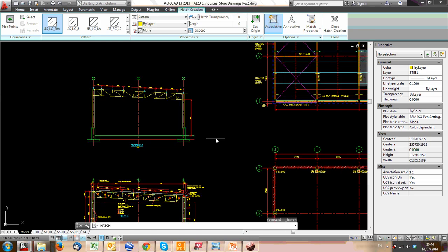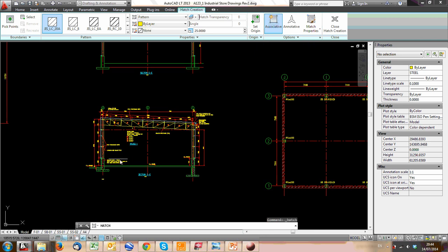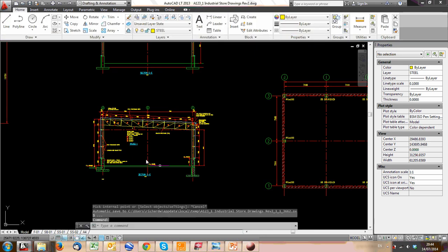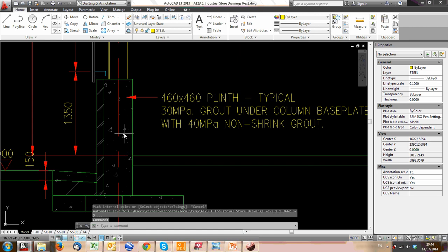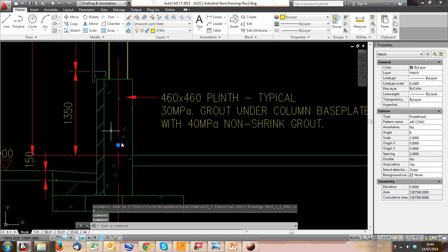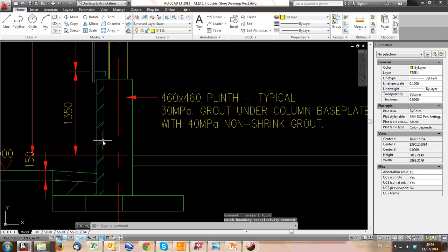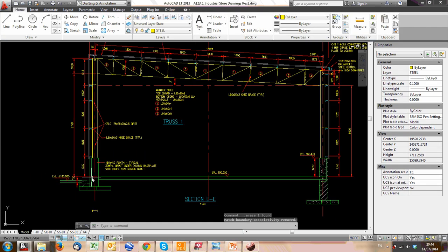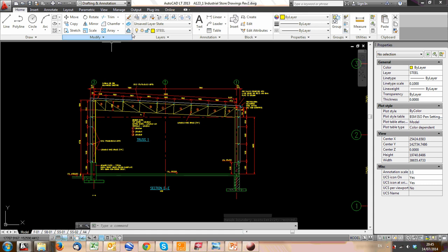Alright, so that's where we got to in the second lesson. Now we're going to continue with this, but I think it's just going to be faster to continue with it down here. We now need to add some hatching to this. Hatching is the sort of fill, this colouring in that you do. I'm going to delete the hatching we've got there already. If we want to fill up those areas with the hatching to show what it is, we've got a hatching tool here. There we go.